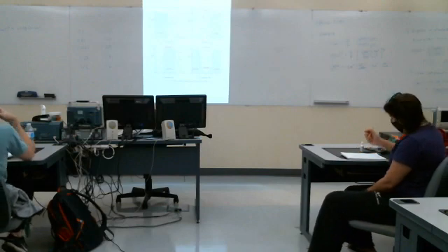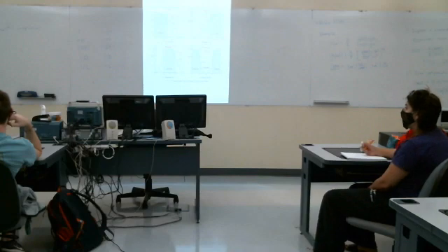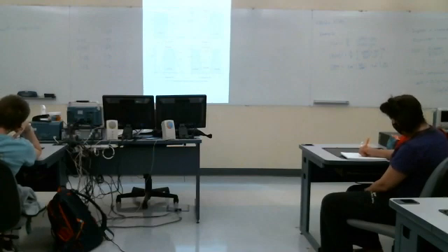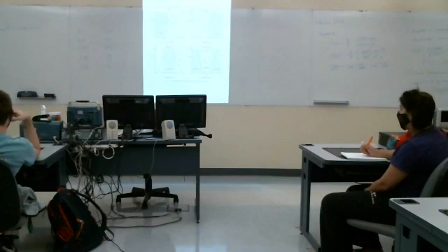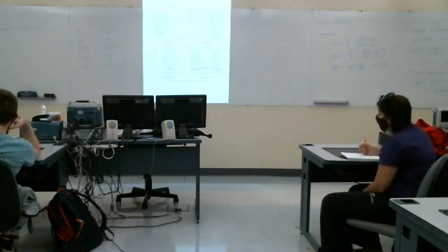That's 40. So that would actually double. What do you think it is at 1,000 omega c? 60. So this actually goes up at a 20 dB per decade rate for a term like that. So it's a straight line. That's the key thing. And it would go up forever.